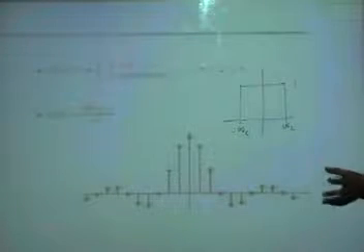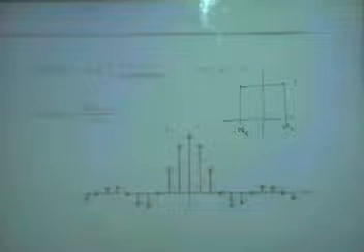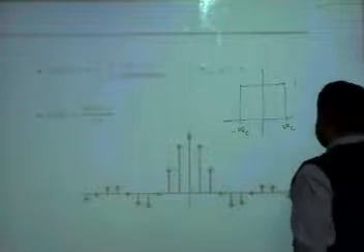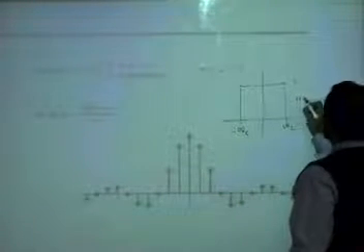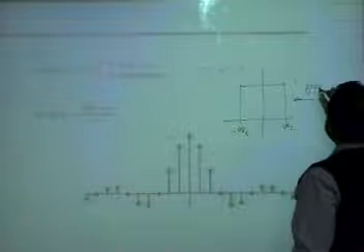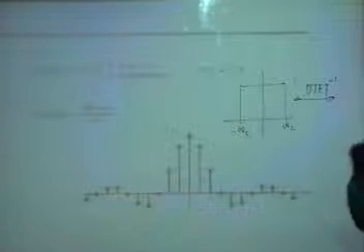So I say, okay, if I make this, then I take the inverse Fourier transform. I can always do that because I know the formula. Why first have h of n and then take the Fourier transform to visualize? Why not design, plot what I want, and then take the inverse Fourier transform? There is no harm in it, obviously. So I say, let me take the inverse DTFT.